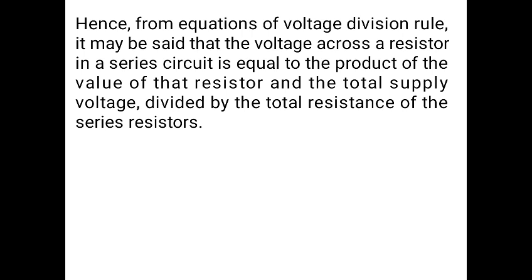It may be said that the voltage across a resistance in a series circuit is equal to the product of the value of that resistor and the total supply voltage divided by the total resistance of the series resistors.